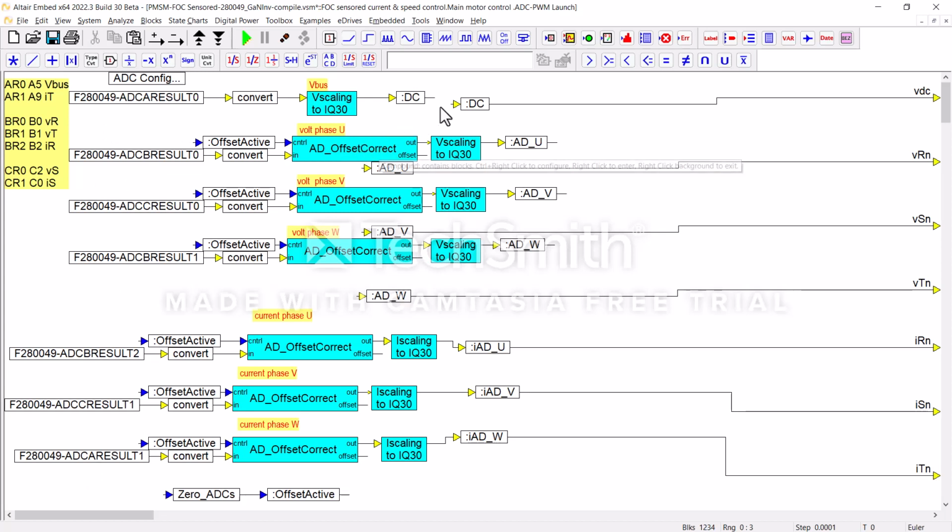So when the machine first boots up, it stages a few things. One is it waits for the inverter itself, the DC bus, to settle, and then it zeros the PWMs for both current and voltage. There's 3 current sensors and 3 voltage sensors on the gallium nitride inverter. And it does that by putting out a 50% duty cycle during that period and expecting there to be no voltage differential between any of the phases.